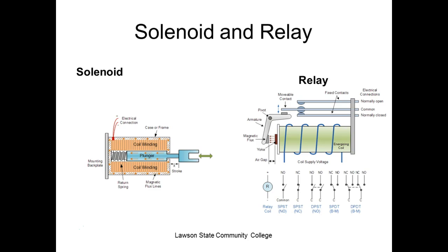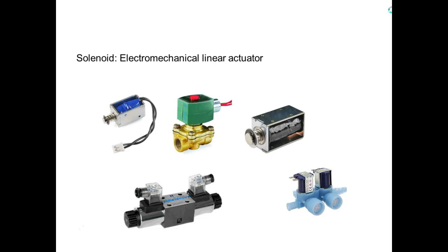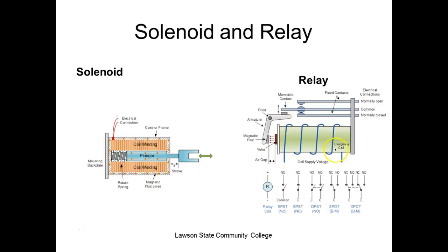So we got relays, and a contact is something that we make and break. So you can see this relay right here. I come over here and put current through this coil. We call this a coil because it's just wire that's wound in a coil, so we call it a relay coil. And then I put current on there, it generates a magnetic field, pulls this thing down, and moves that, and does what? Opens one set of contacts and closes the other. But now instead of me doing it manually, I'm controlling it electrically.